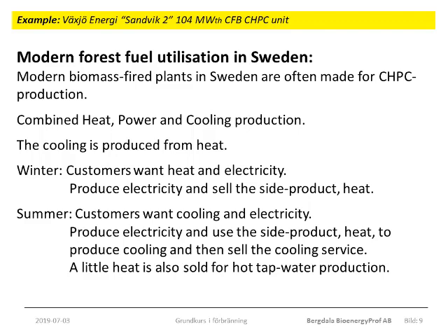In that case, you sacrifice a bit of the electricity, but in some climates the heat demand is big enough to make this a feasible option. This is called district heating, and the process is CHP, combined heat and power production. But in summer, you will not be able to sell very much heat. And if you limit your heat production, you will also automatically limit your electricity production.